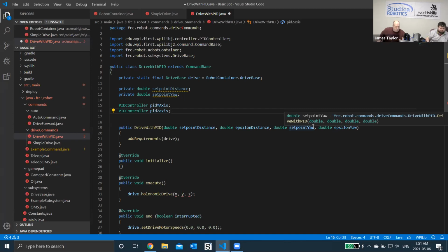Right. It's important when you're doing this code for this PID, and you have to remember this, that's why in this robot design, the VMX is centered on the top of the robot. And remember, we talked about the front of the robot being where the OMS is, the object management system. The default orientation for the integrated motion unit is that the front of the robot matches the direction of the Studica logo on the front of that VMX, which is your Y. So if you mount your VMX somewhere else and try to run this code, you're not going to get the right data.